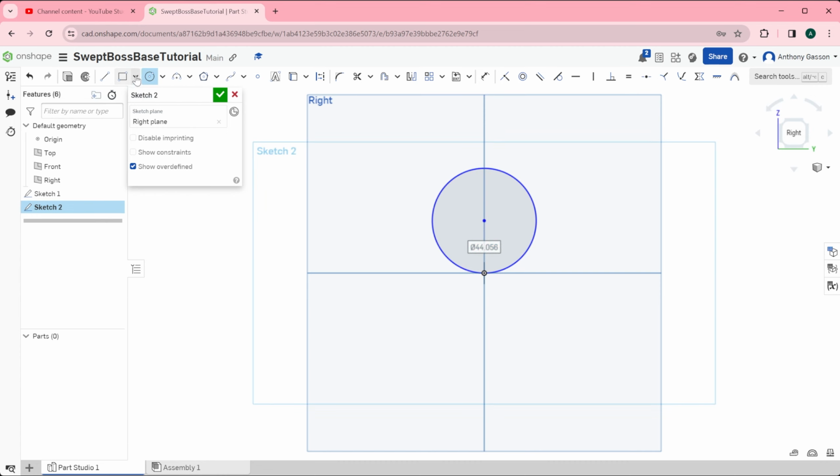I'm then going to use the rectangle tool to take a section of this path out, and use the trim tool to remove all of the unwanted lines. In this particular sketch, the sketch is not closed. Because this is a path, it is okay for this sketch not to be fully closed vectors. I'll now click the tick.